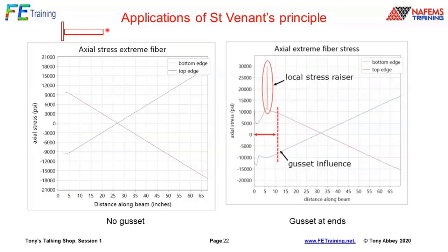Now, because it's constrained, it's basically a center section here, then we get actually a reversal of bending. So we get a reversal of the bending stresses. If I draw the center line on here, that represents the extreme fiber stress top and bottom at that station due to the root bending, and the reversal of bending somewhere around here due to the center line.